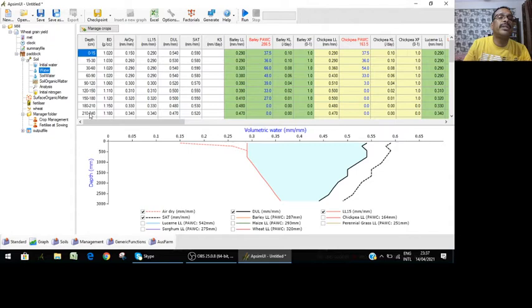that the soil depth is up to 2 meters, having bulk density. These things, if you have your own bulk density, simply you can click it and change it by yours. You can change the depth, the interval also. If it's 0 to 10 or 0 to 5, you can make it also. If it is 15 to 30, it is 30 to 45 or 30 to 40, something like that. There is nothing wrong. You can edit anywhere, any part according to your choice. So what we'll do, you can put your own data set here according to the properties of your soil profile, then air dry, then lower limit means plant permanent wilting point, PWP or percentage.